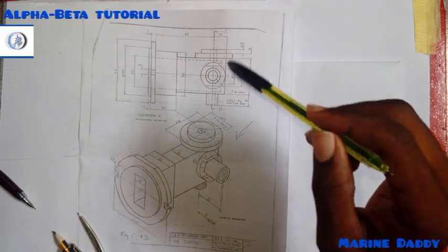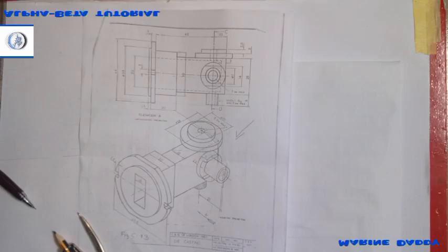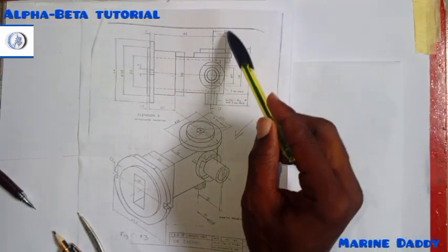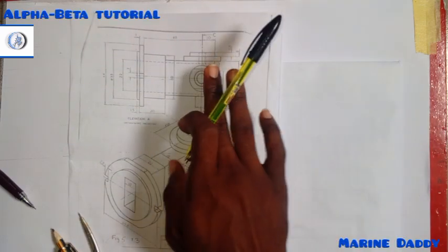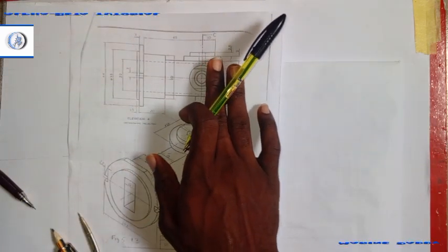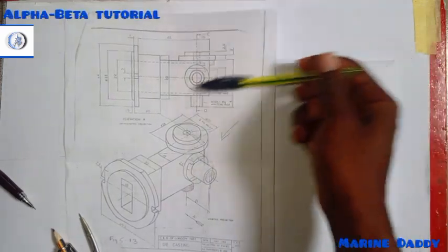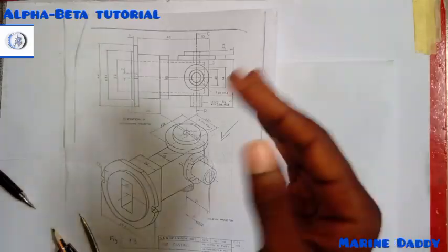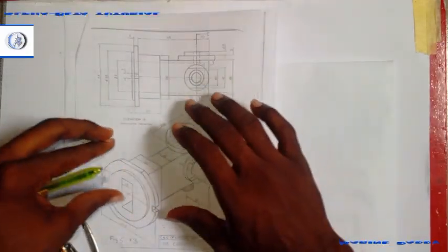Understand? So the question says find the CD, the sectional view CD. Now the arrowhead is pointing towards this direction. So which simply means that you are to cut the back of the structure, then view it from that side. The surface of the part that has been cut is what you're supposed to represent. You understand? And this is my front, this is my diagram itself.